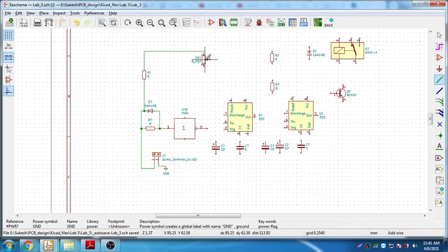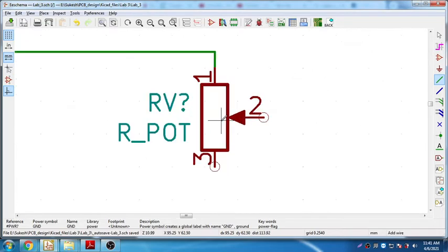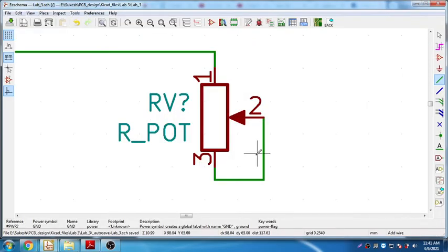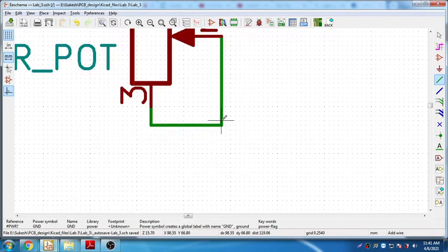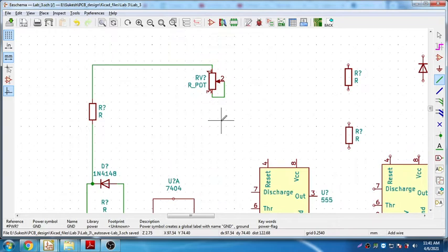So in the port, if you see, zoom in. I need to short either 1 or 2, and 1 or 3, depending on what we need. Okay, so I will short these two. If you look at the circuit, you see here it is shorted. Okay, then it goes to 7. So 6 and 7 I need to make it short.